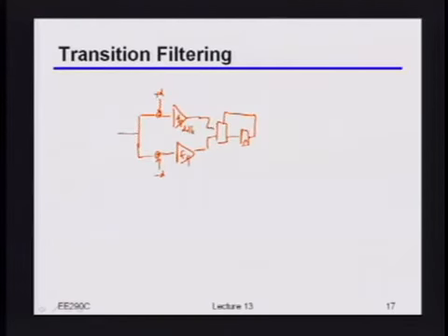So in this context of, for example, the loop unrolled DFE, you might do something where you didn't want to build all of those samplers, but at the same time you didn't want to suffer the penalty of trying to track the very different timing estimates that you might be getting. This again may be your data path. But what you could potentially do is, on your edge path, instead of having all 3 of those samplers, you'd only have 1, right?